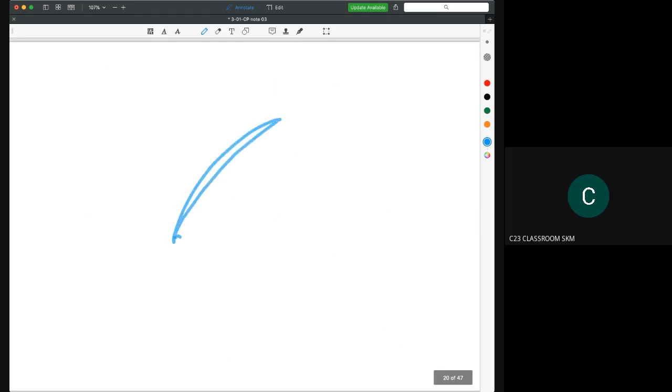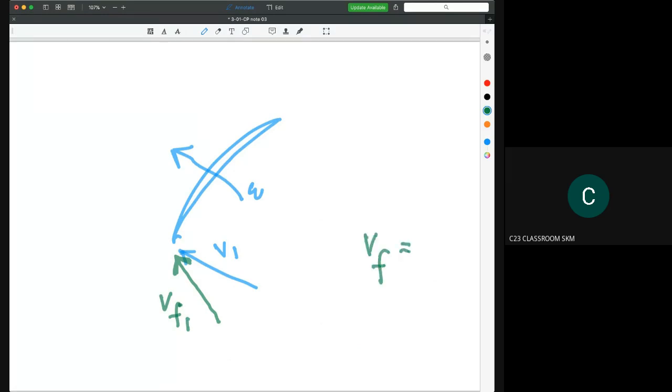So what happens to our velocity triangle? We have the blade here, rotating counterclockwise, from right to left. This is our real velocity, V1. And if the fluid flows without any resistance, it will flow in the radial direction. So we call it VF1. The VF here refers to the flow, meaning the ideal flow, flow without any resistance. Okay, why?